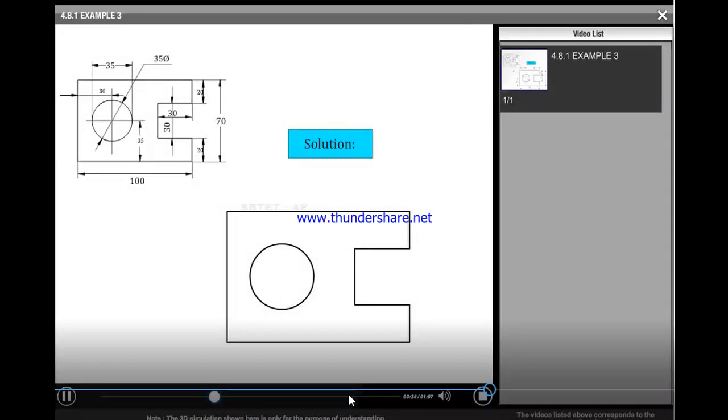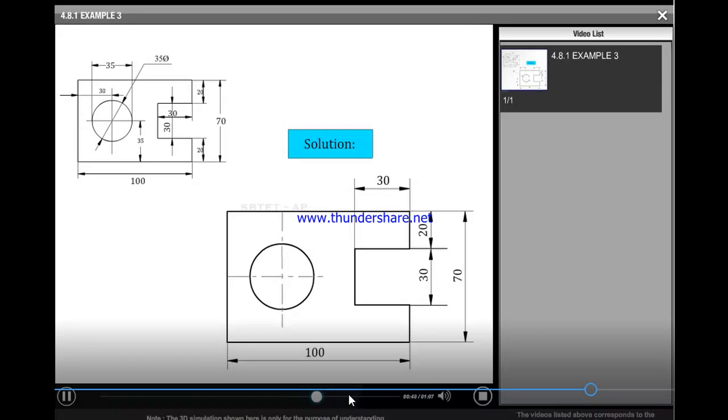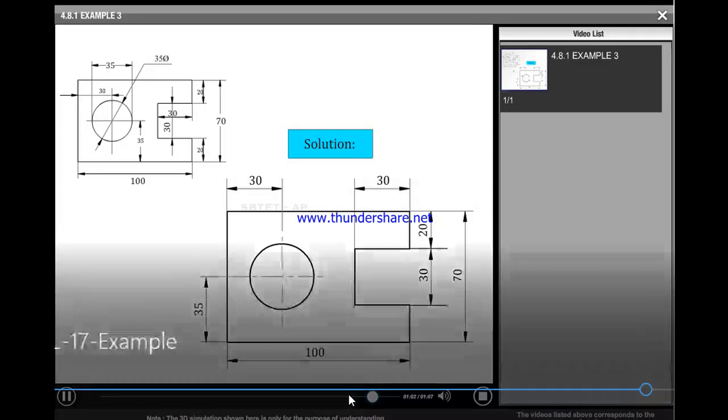All the dimensions are to be shown externally. Represent the dimensions in an aligned manner. Keep the symbol for the parameter clear of the numerical value.